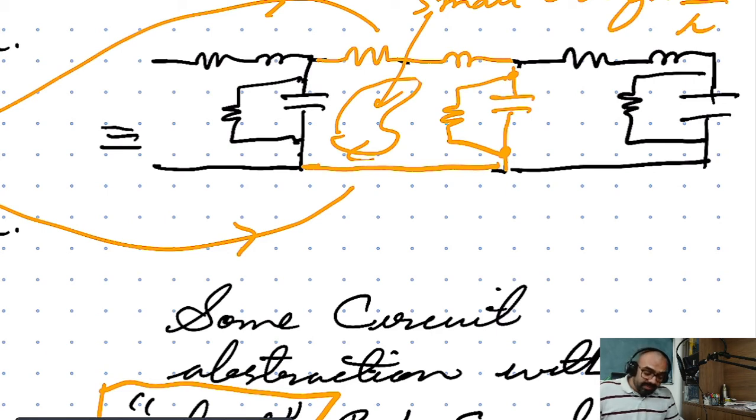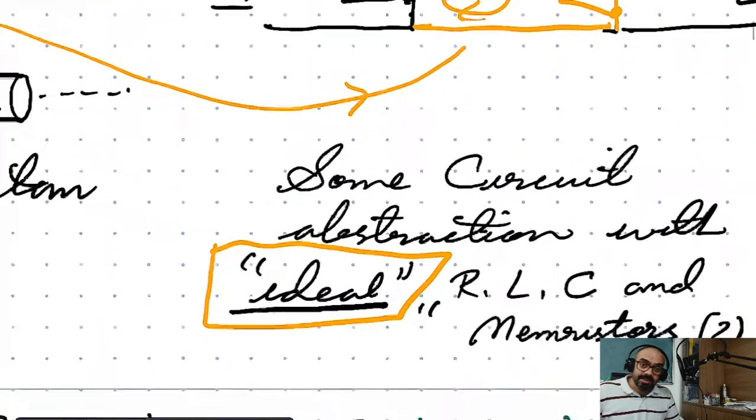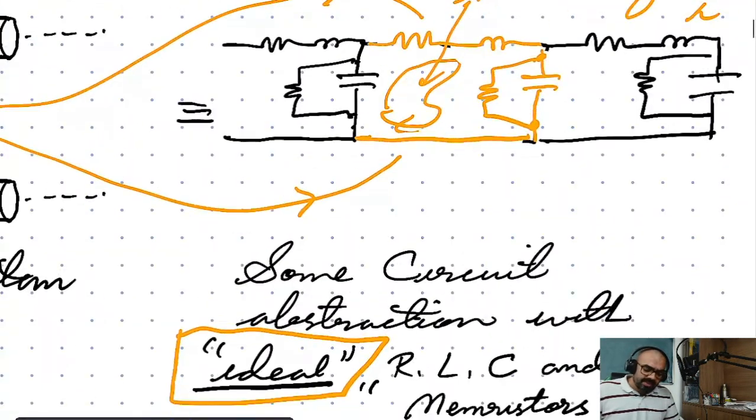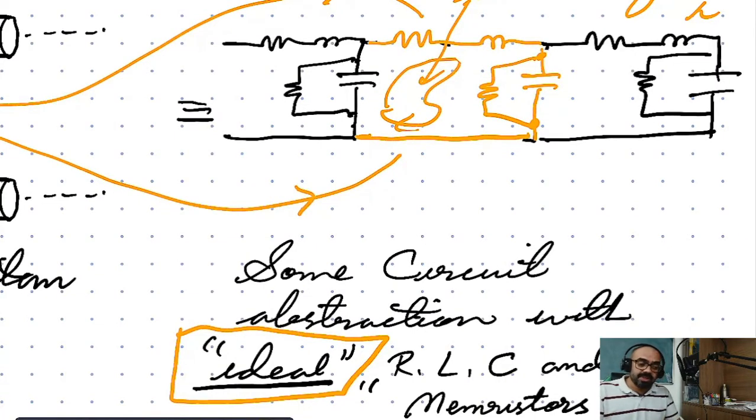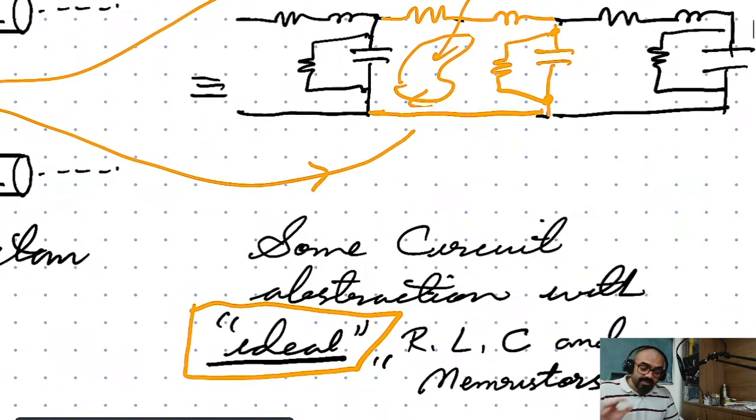Luckily, what we find out when we proceed with the analysis of transmission lines is that the exact calculation of R, L, G, C parameters need not be required in all cases. Sometimes you can simply measure things and deduce these properties. However, I do want to point out that if you want to calculate them exactly, then you do need to do field analysis.